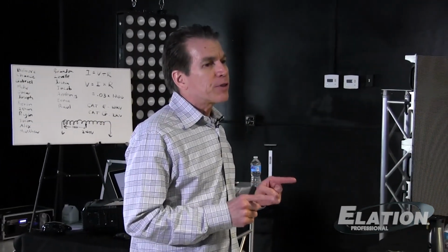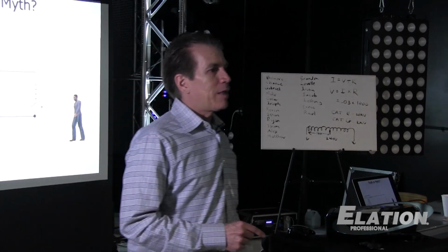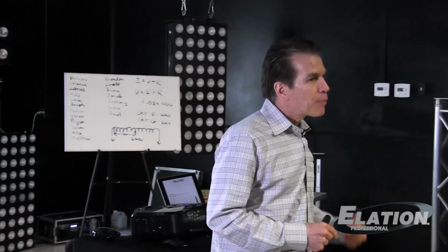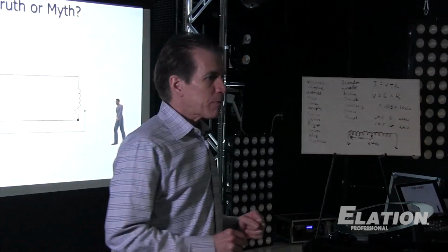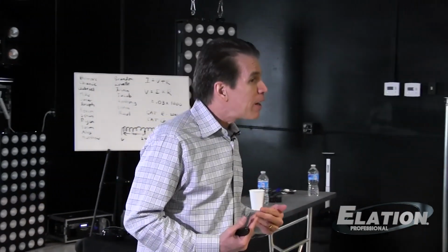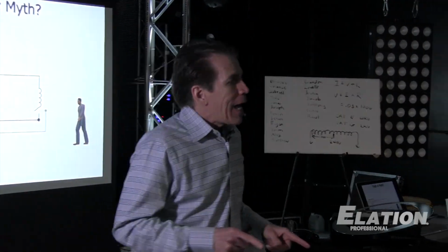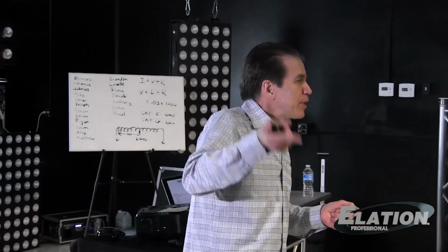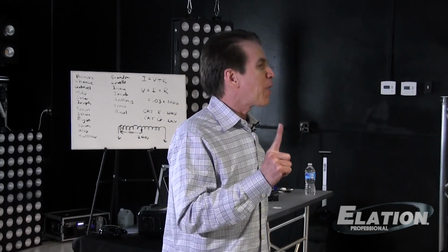Now that voltage difference should not be great. Typically you want it to be less than 2 volts. But in lots of instances, it's a bit higher than that. It can be 5 volts, it can be 7 volts, in which case that's not the ideal situation. What I would do in that instance, if I have time, is go around shutting things off and measure the voltage, and then turn things on one at a time. Because in some instances, you'll find there's one piece of gear that's causing a lot of problems.